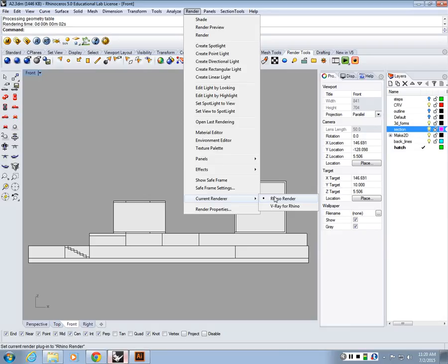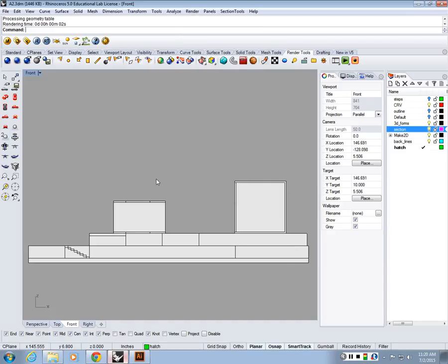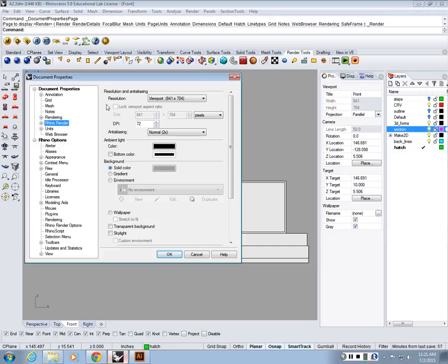We're just taking a rendering shot with shadows, and you're just going to use it to lay in the background of our drawing. It's really simple production. It's a really simple pipeline. So go here, switch to Rhino render, and then you can do this though. You can go to render settings and bump up your resolution for your rendering. So you could do the resolution, let's say 3200 by 2400.